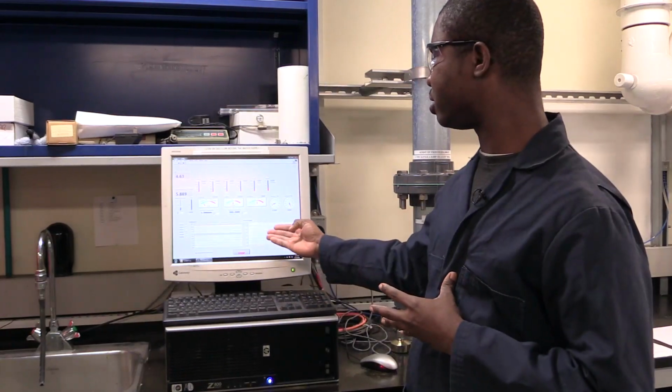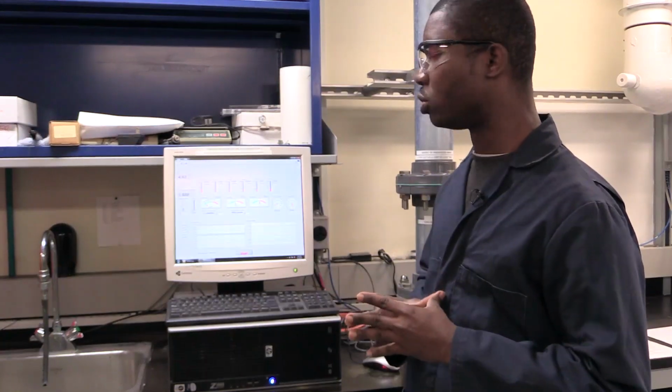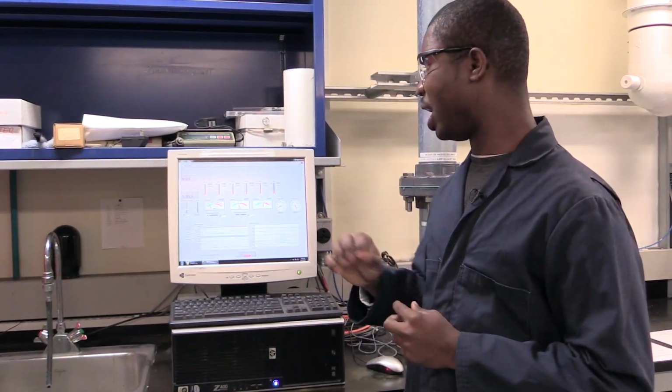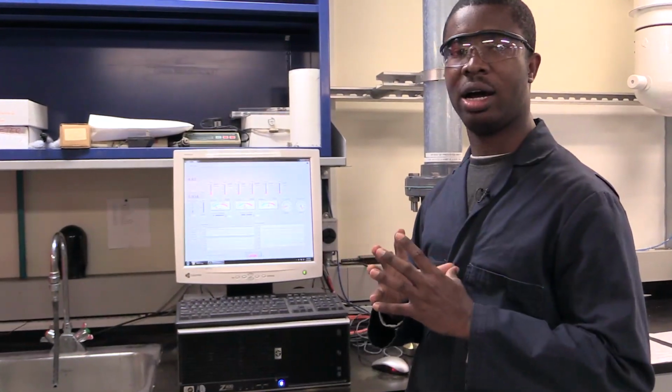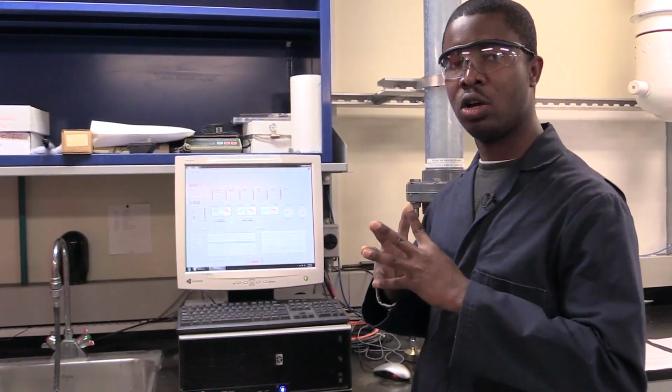As you can see, the system is pretty much at steady condition. So we'll move to condition 2. Condition 2 is to increase the flow of CO2, to double the flow of CO2 and drop slightly the flow of air such that the total gas flow remains constant at 2.5 standard liters per minute.